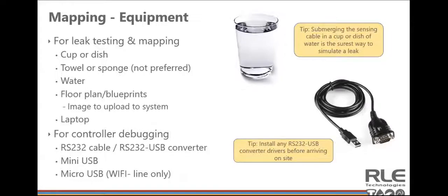So another thing just to have handy for debugging is debugging cable. For a lot of our controllers, it's a 232 cable. If you have a laptop, you might need a USB to 232 converter. So I just want to warn you, make sure that you have the drivers installed beforehand, because you might need access to the internet, and at a remote site, you might not have that.